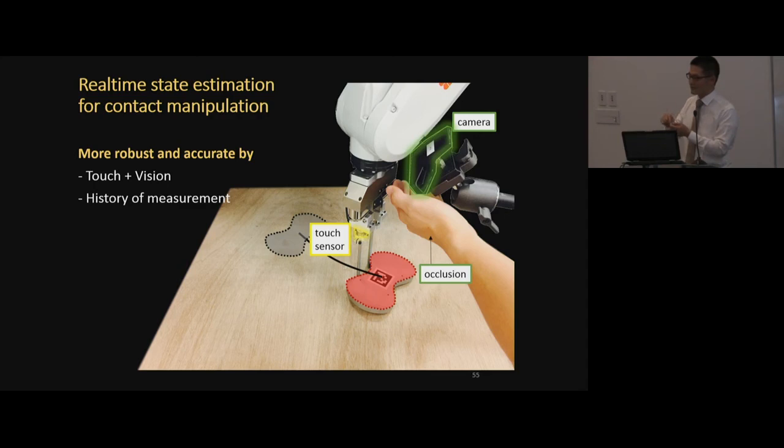It's possible to have just 1-point contact there, but it's not the major type of contact that we will encounter. So there's a policy when selecting the contact formations. We try to eliminate the minor contacts, and we want to keep the set small so that the accuracy can be high enough.